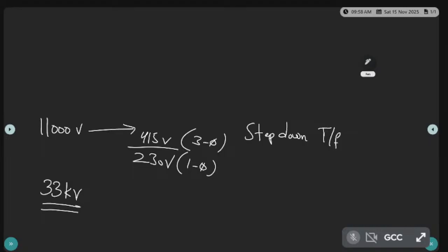Okay. Hydro, Nagarjuna Sagar, Srisailam, their power is generating. So the voltage level, I'm talking about only voltage level. Voltage level is 33 kV. So this has to be increased to 132 kV. 33,000 has to be increased to 1,32,000. Who will do that? Transformer. Here what is the transformer doing? Leveling up. That is step up transformer.